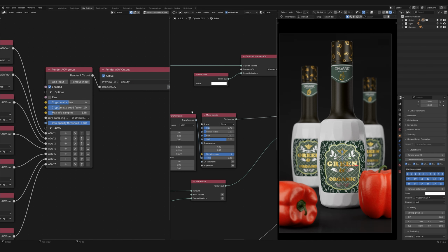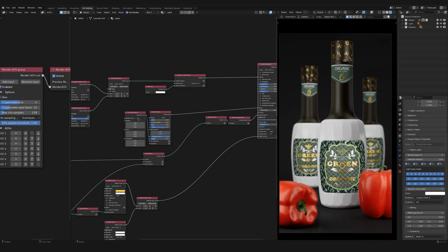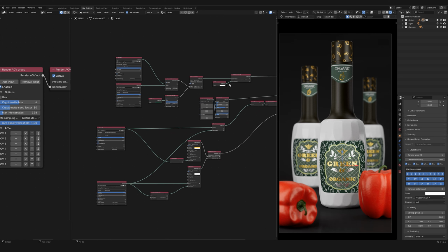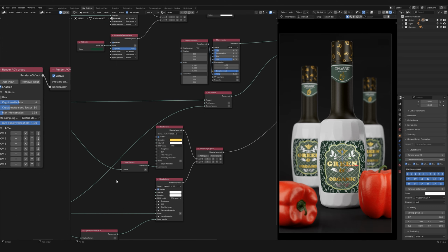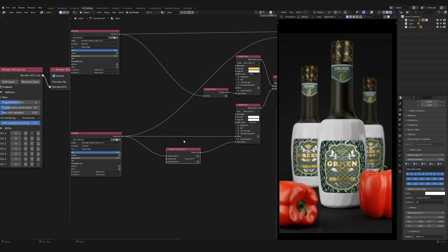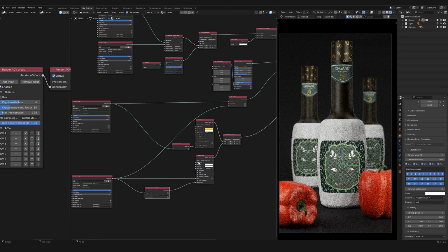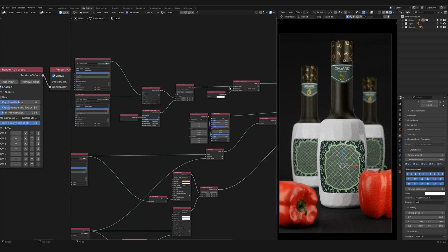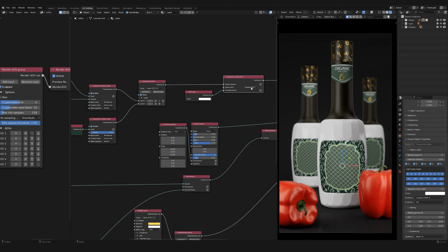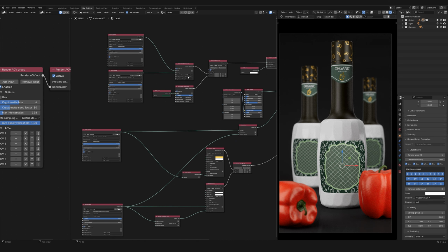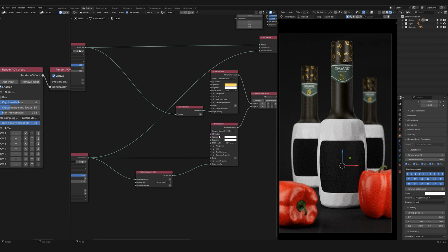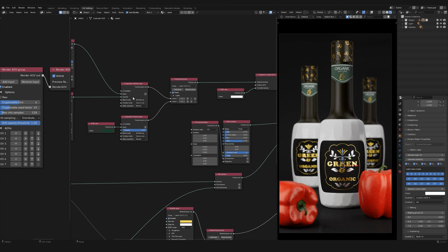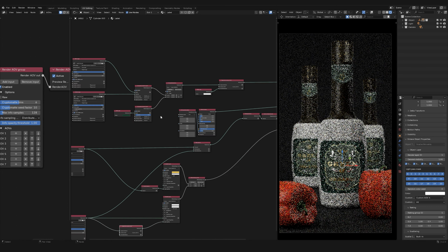In addition, you can assign multiple and different material parameters inside the material. To do this, the custom AOV capture node is used. This label contains several layers. Custom AOV capture nodes have been added to edit label color and foil color. One node creates a mask on the part of the label that contains color information, and the second node creates a mask on the part of the label where the silver metallic layer is displayed.